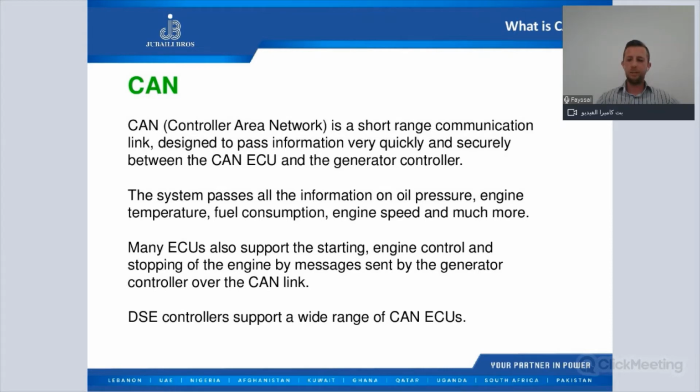Okay, so the ECM reads hundreds of parameters. But what we see on the controller are the only ones we are interested to read. Many ECUs also support the starting, control and stopping of the engine by messages sent by the generator controller over the CAN link. So it's not just about retrieving data or reading data. It's also about sending commands, start, stop, and other control commands.